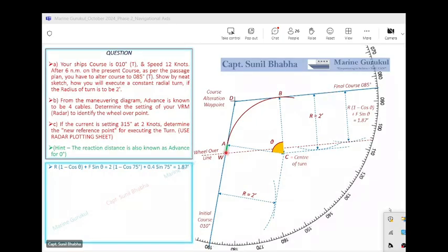However, from point Whiskey going up to Alpha and going up to Bravo is the curved path, and we now need to know how we counteract the effect of the current in this stretch of the passage. So for this, let us first calculate the total time required to cover this passage.